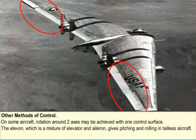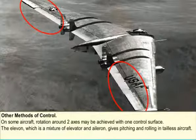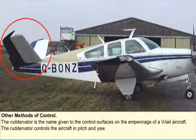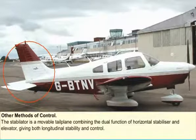For instance, the elevon, which is a mixture of elevator and aileron, is used on tailless aircraft to give both pitching and rolling. The ruddervator, which is the name of the control surfaces on a V-tail aircraft, enables both pitching and yawing. The stabilator is a movable tailplane combining the dual function of horizontal stabilizer and elevator. That is, it gives both longitudinal stability and control.